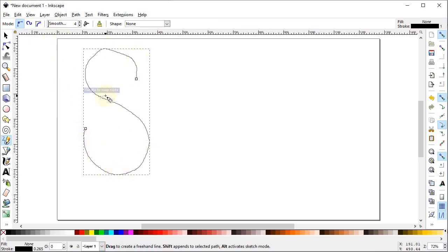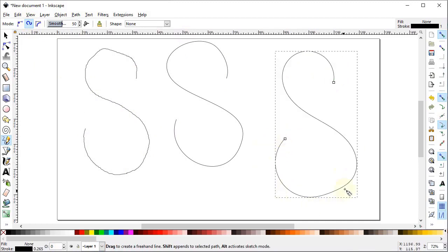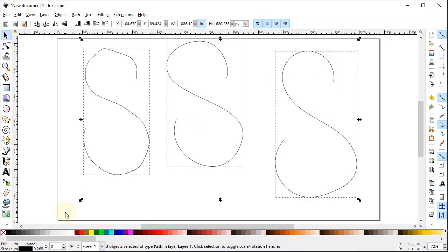to decrease this distortion, then there is the option for the smoothness, which is set to 4. Simply increase its value to 50% like this, and again draw the same shape. And here you can see this shape is much smoother than this one. Now if you want to draw an even smoother shape, then select this create spiral path and again hold down the left mouse button and drag the mouse in a manner like this, and you can see this shape is even smoother than this one.